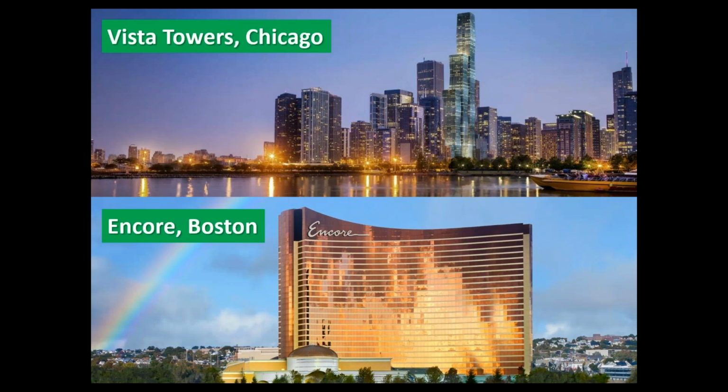Okay, so there are some case studies and examples that I would like to discuss here. The smart sensors in particular have been used, as I mentioned, worldwide in 4,800 projects. Most notably, Vista Towers in Chicago, which is about a 100-story tower, all post-tensioned. Basically, they relied on smart sensors to know exactly when they can pull the cables, and they completely eliminated the field cure cylinders to speed up their process.